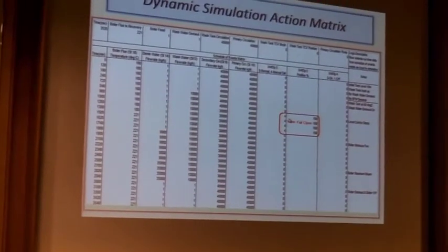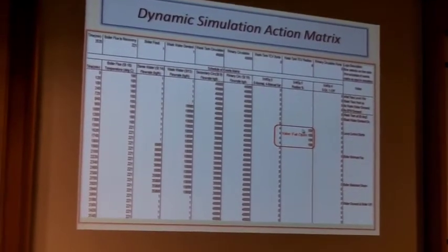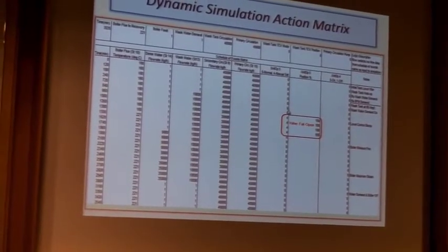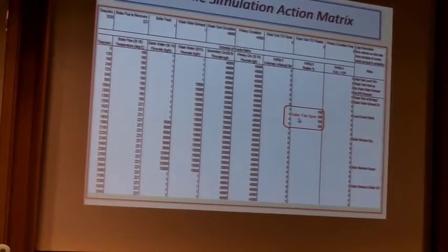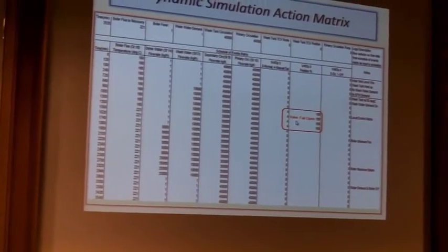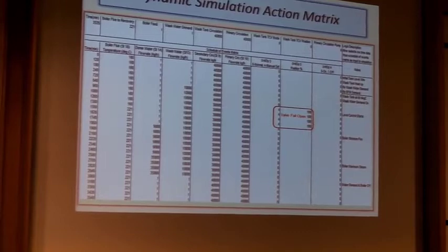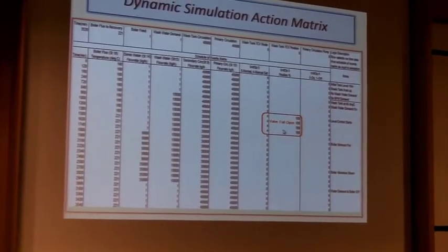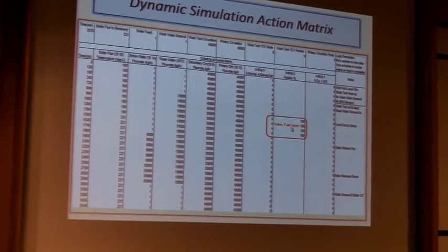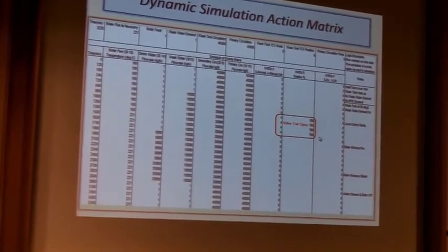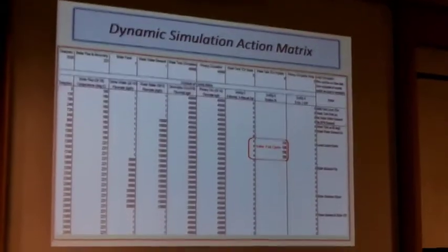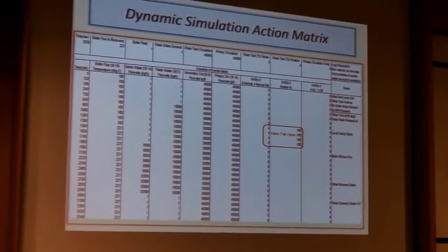But I can also fail valves. So what I'm showing here is, just by injecting certain parameters in here, I can make the valve that normally fails closed fail open just to see what happens. It's just jammed open. And I've done that for 6 hours. You'll see what that looks like on the response. Very powerful. So you come out of a HAZOP and say, well, I'm not too confident about your control system, and you can show the demands on the control system and see how it responds.